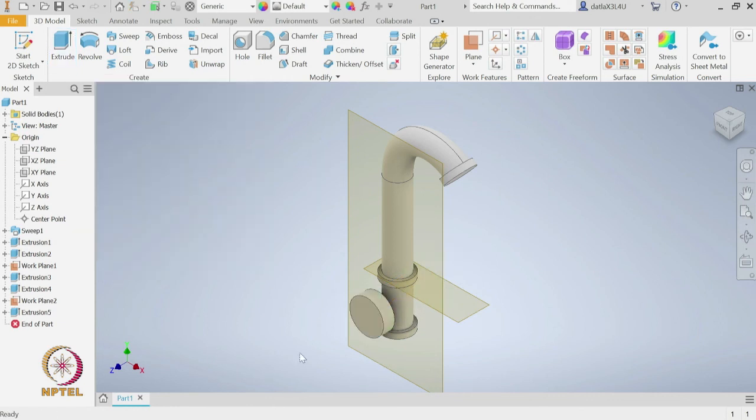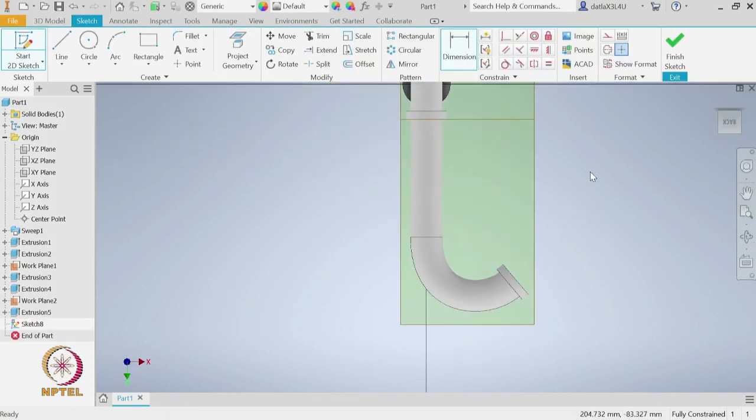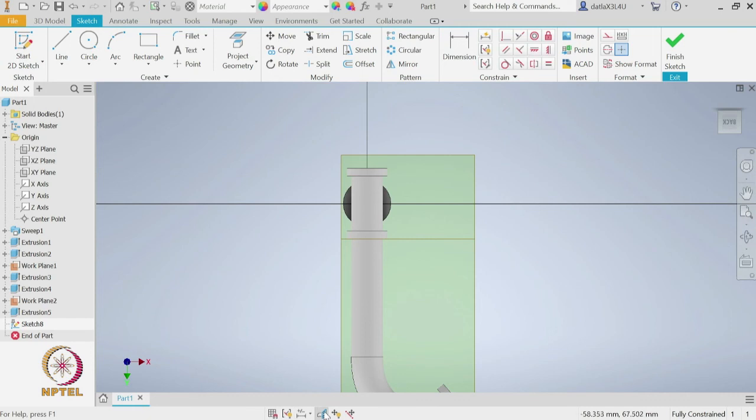Okay. So, we have created this circular cylinder, but now we need to connect this circular cylinder to the vertical column. For that, what we will do is again choose extrude and select this end of this circular cylinder. Now let us choose this slice graphics, so that we can get rid of this vertical column for the purpose of drawing the sketch.